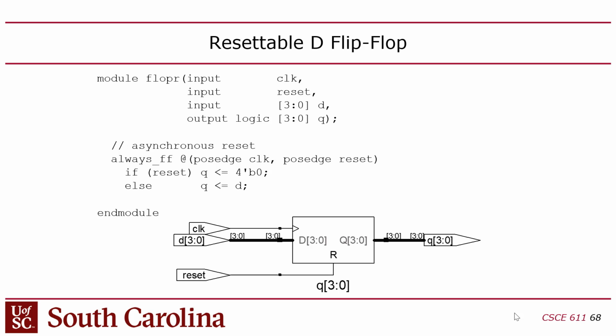So for example, your program counter in your CPU will be built this way. Your program counter needs a reset, obviously, because that's how you reset your computer. You hit the reset, it sets the program counter to 0, and then it starts fetching instructions starting at address 0, which is your bootloader. But does it matter if that reset is synchronous or asynchronous? Probably not, right?